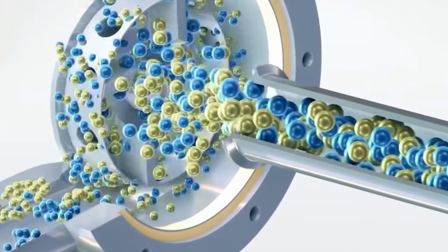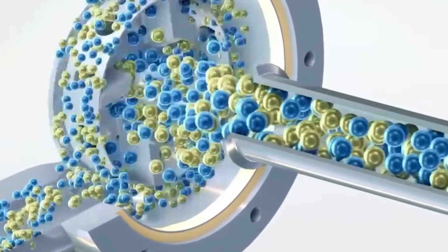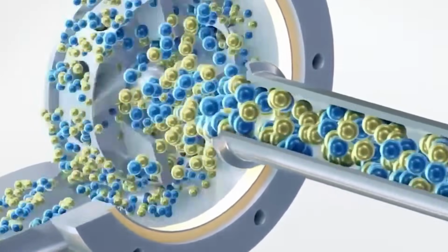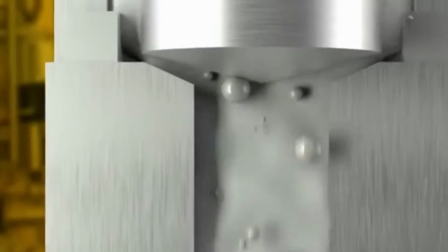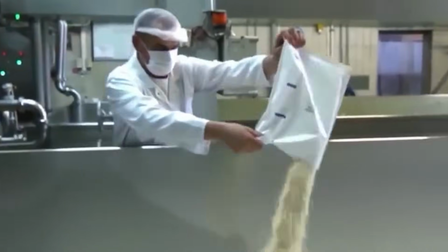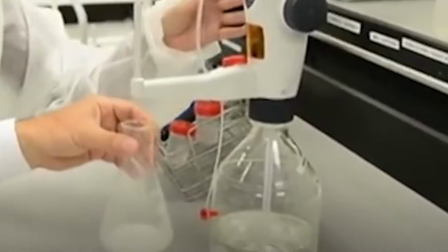The rotating blades prevent ice crystal growth by constantly scraping the frozen layer from the barrel wall and remixing it into the semi-frozen matrix. During freezing, air is incorporated into the mix to achieve a desired overrun of 30% to 60% by volume, much lower than regular ice cream, to maintain the dense, creamy consistency associated with frozen yogurt.